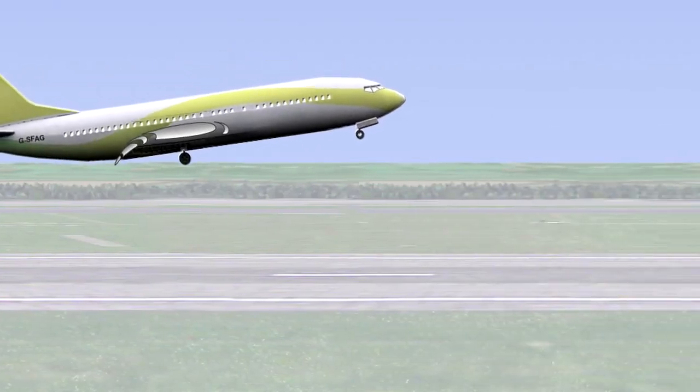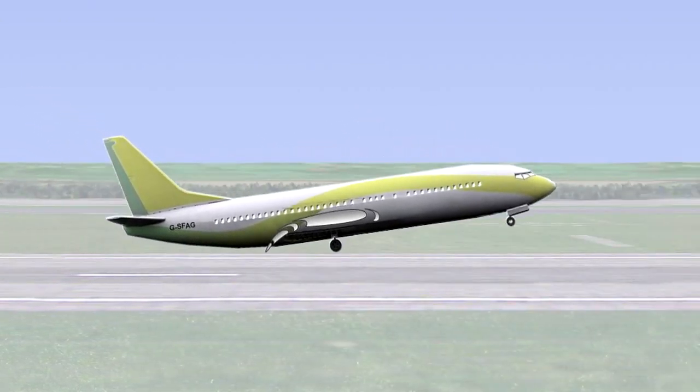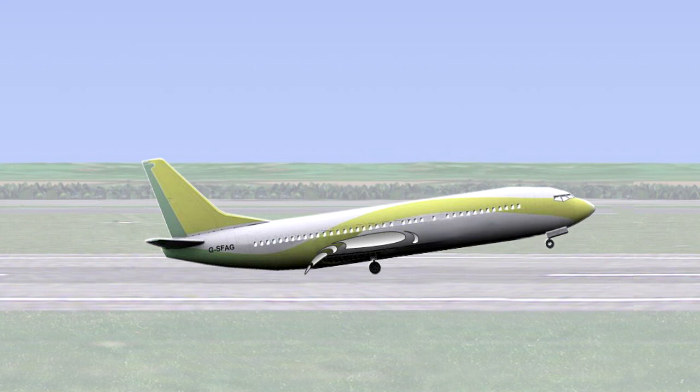The flare should lead to a firm touchdown, sometimes described as flying the aeroplane onto the runway. Positive landings will help place load on the wheels, which will increase braking effectiveness and squeeze out the water from the tyre footprint area. Do not allow the aeroplane to float, and do not attempt to achieve a perfectly smooth touchdown. An extended flare will extend the touchdown point. Soft touchdowns will delay wheel spin-up and delay oleo compression, which is needed for auto brake and auto spoiler activation.